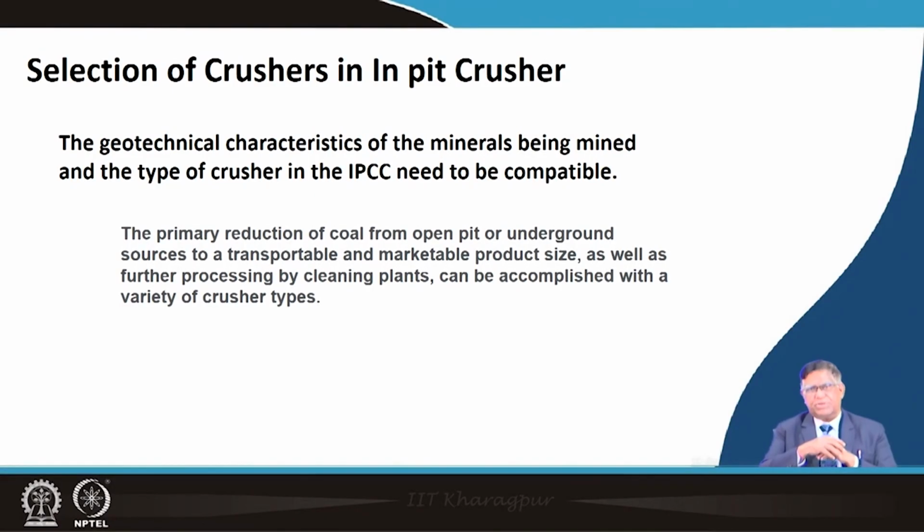The crusher was purchased from Germany, brought and installed. But the overburden there had a lot of clay and was sticky in nature, and whenever they wanted to send it through the crusher, it often got choked and the material was not going out.